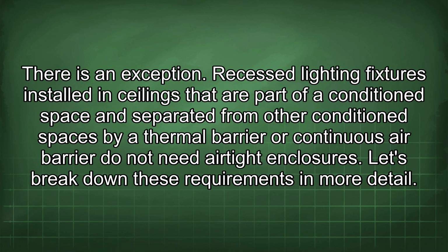There is an exception. Recessed lighting fixtures installed in ceilings that are part of a conditioned space and separated from other conditioned spaces by a thermal barrier or continuous air barrier do not need airtight enclosures. Let's break down these requirements in more detail.